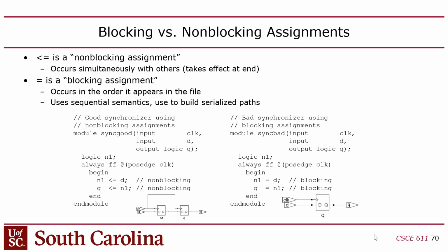The exception to that is the code that's inside an always. The whole point of an always is to create a little island of code that has sequential semantics. That's the reason why I was able to, for example, give out1 a default output, and then right below it have an if statement that changes it potentially. That's sequential semantics.